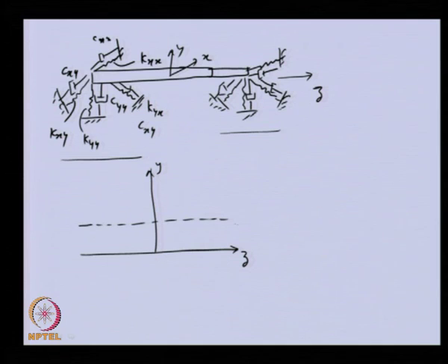So, I am giving a displacement in the y direction, and we expect because of this there will be displacement in x direction also, in the other orthogonal plane. And earlier we had both the radial and axial eccentricity of the rotor. So, this is the axial eccentricity in the z direction, and because it is rotating, we have this centrifugal force which is offset from the center of